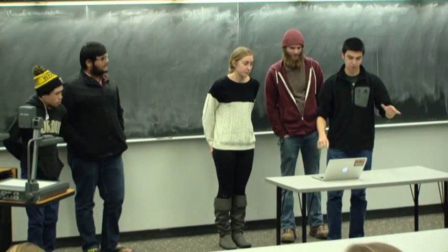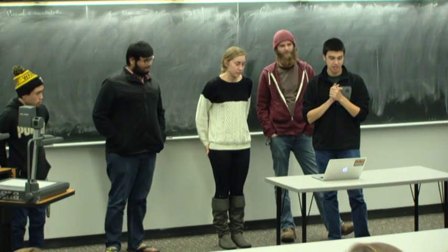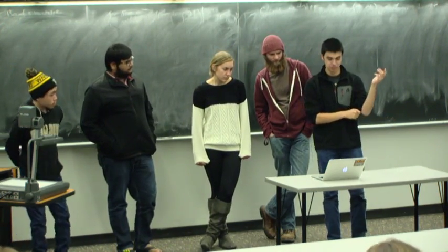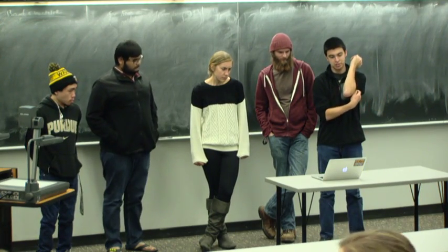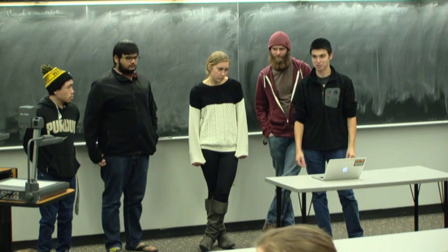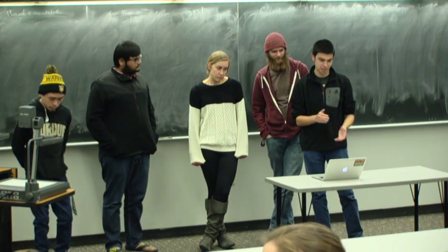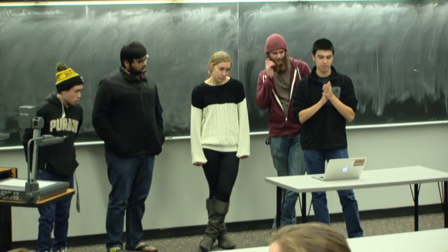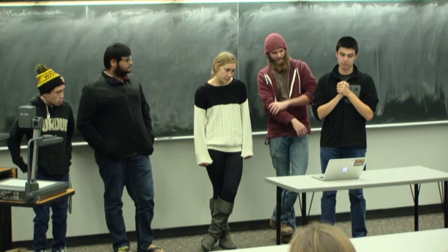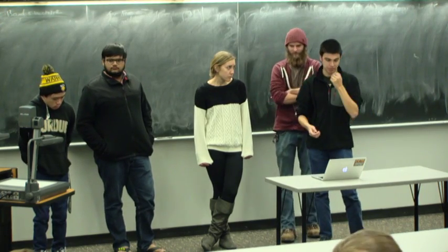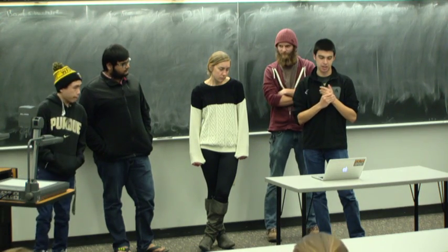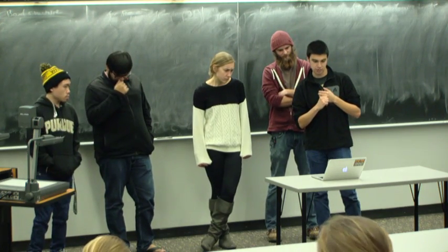Okay, so for our first process function, we have video quality. A potential failure would be if it's strongly pixelated. The effect of that would be frustrating to use, and the severity was 9 because that's the purpose of a webcam, to talk to someone on video. A potential cause of failure would be a bad camera lens unit, so we put that occurrence at a 4, because if you're checking your manufacturing, that shouldn't happen too much. For current process control, we said using high quality materials, and the detection of that would be a 2.